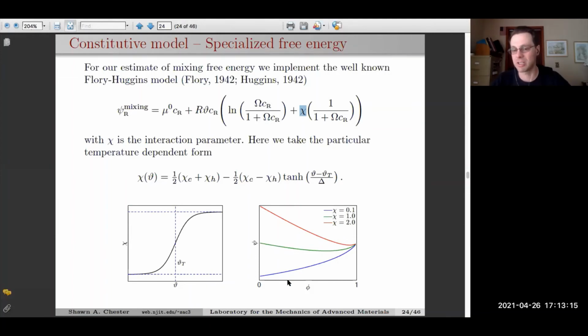So this is just a schematic essentially showing the energy of mixing versus polymer volume fraction. So 1 is a completely dry polymer. As you go towards 0, there's more and more fluid. And what I want you to notice here is just simply based upon chi, I know there's no numbers on the energy axis, but the blue is always negative, the red is always positive, right?